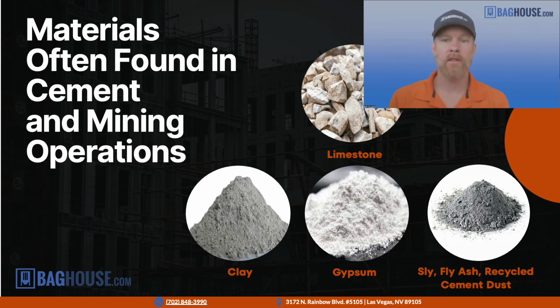So it's worth taking a moment here to think about what I am dealing with in terms of raw materials. What is the dust at my part of the process? Because each material behaves a bit differently in the dust collection system. Some materials, maybe in the crushing process, are coarse and abrasive. That dust is treated a little bit differently than a really fine dust or a hot dust that might happen later on in the process and might be more prone to carry over, floating around the facility or the site, building up on your equipment and your floors and so forth.